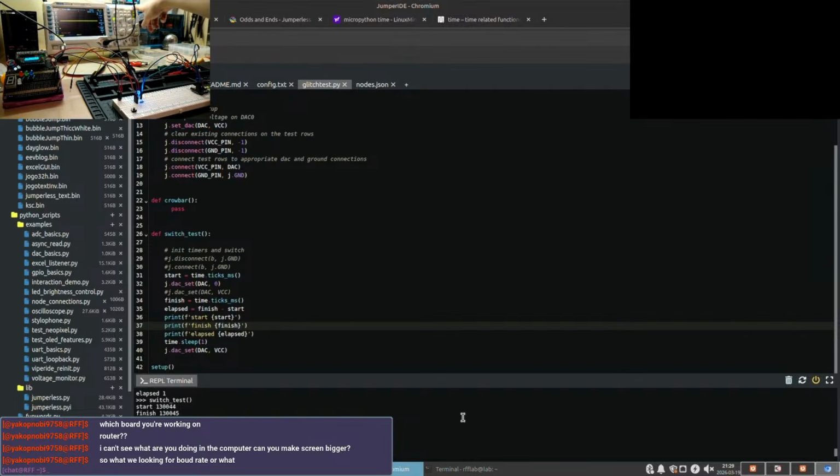What about if we do that? Maybe it's catching the beginning of it and not all the way down at the bottom? Oh, I'm dumb. It's only catching how long it takes to go off, because I'm delaying the on time. So let's see if we can catch the rise time with this measurement. It says the rise time is about 3.94 microseconds. That's a bit faster.